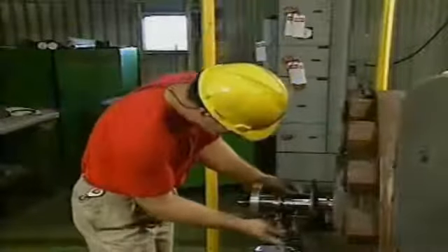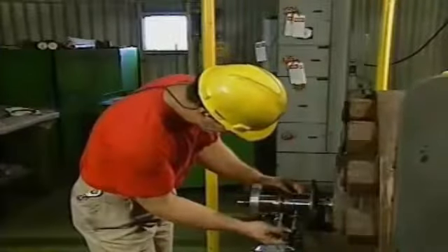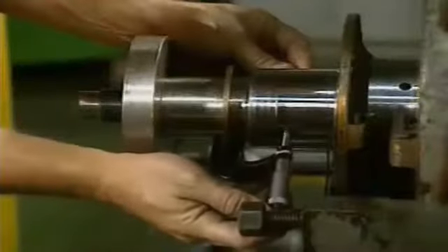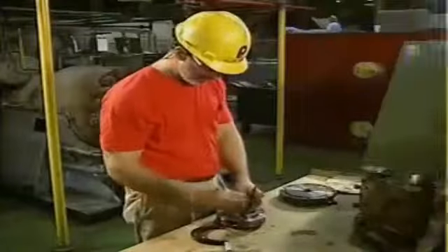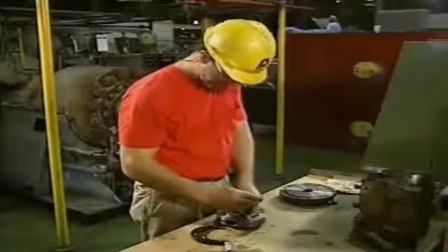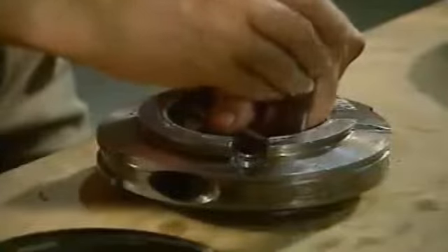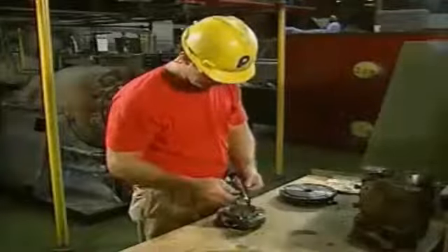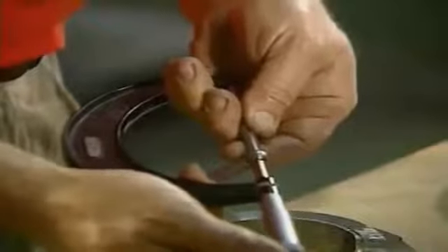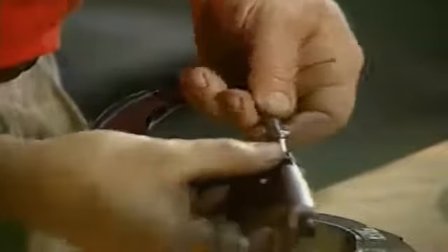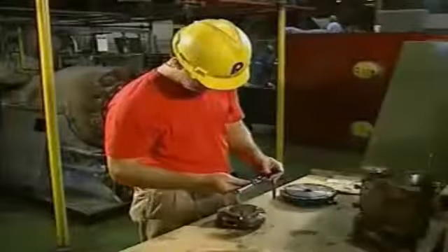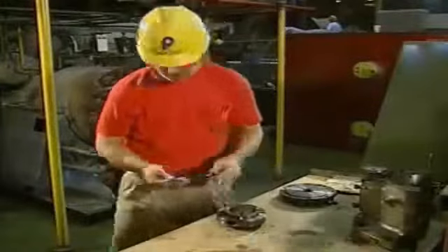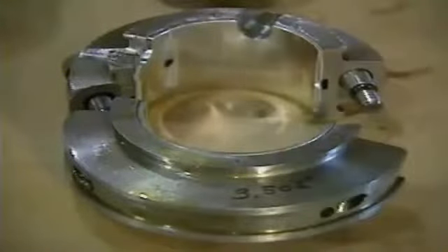The mechanic will use a micrometer and a T-gauge to check the total clearance. First, the mechanic measures the diameter of the shaft with the micrometer. Then he positions the T-gauge inside the bearing. The mechanic sets the T-gauge to the distance of the inside diameter of the bearing, and then he measures the T-gauge with the micrometer. To obtain the total clearance, the mechanic subtracts the diameter of the shaft from the inside diameter of the bearing. If the total clearance is too great, the bearing inserts are replaced and the test is repeated. If there is too little clearance, the bearing is either replaced with a bearing of the correct size or else it is scraped down.